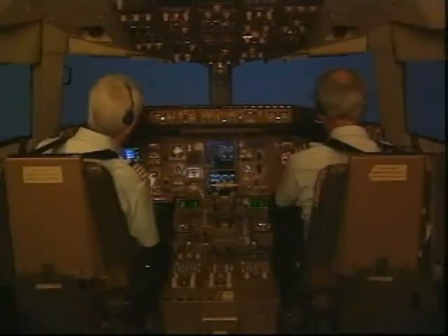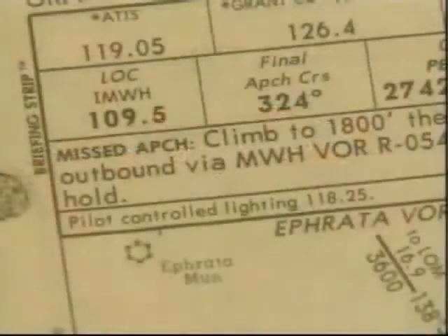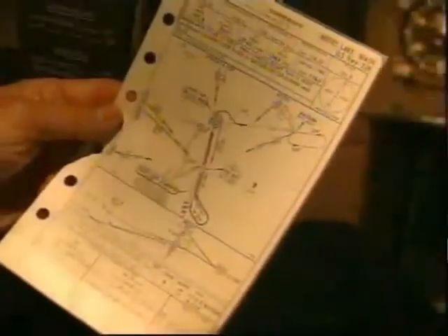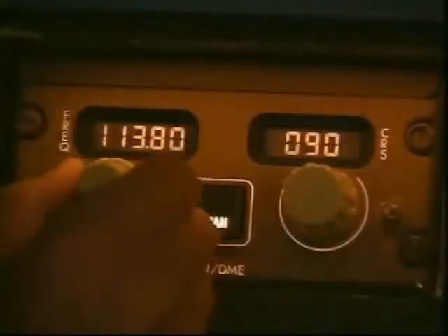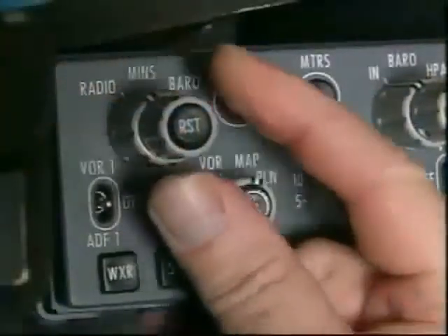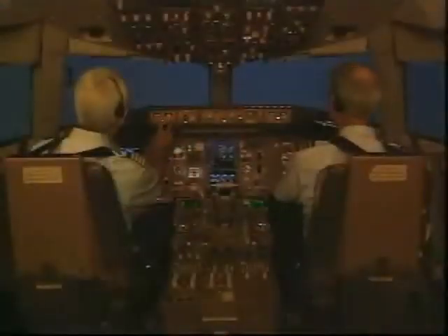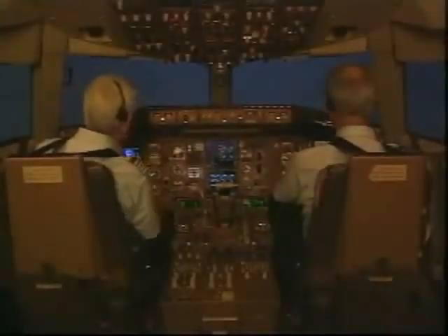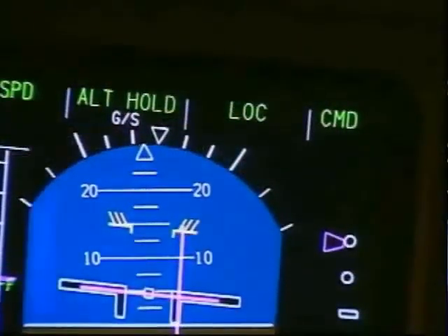A number of specific items must be a part of the approach briefing. As previously reviewed, the crew must discuss, plan, and prepare for the possibility of a go-around. The briefing should include a discussion of the use of all available navigation and approach aids appropriate to the approach being flown. A discussion of the use of the radio altimeter should also be a part of the briefing. To avoid confusion, the discussion should include the use of automation on the approach, as well as the circumstances when the use of automation will be discontinued.